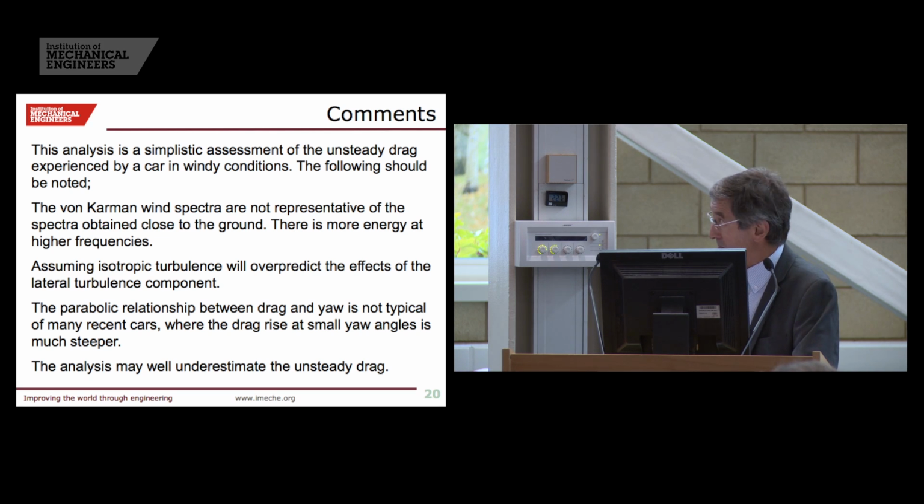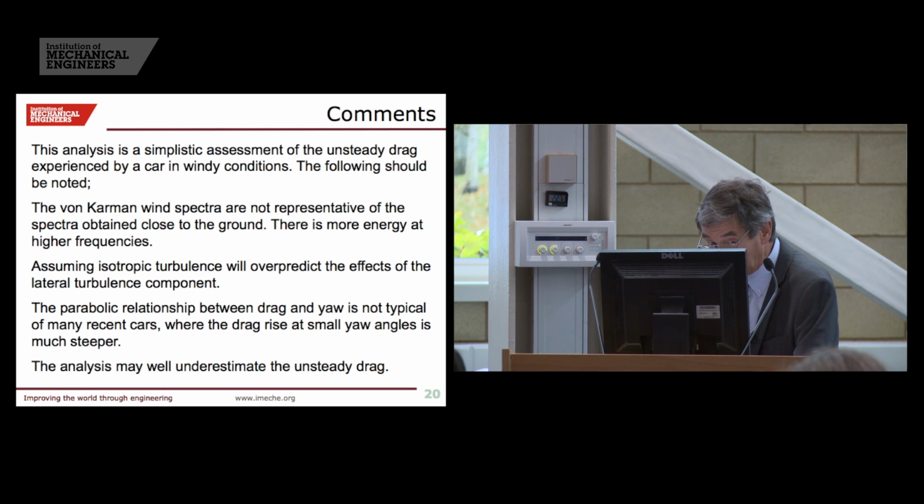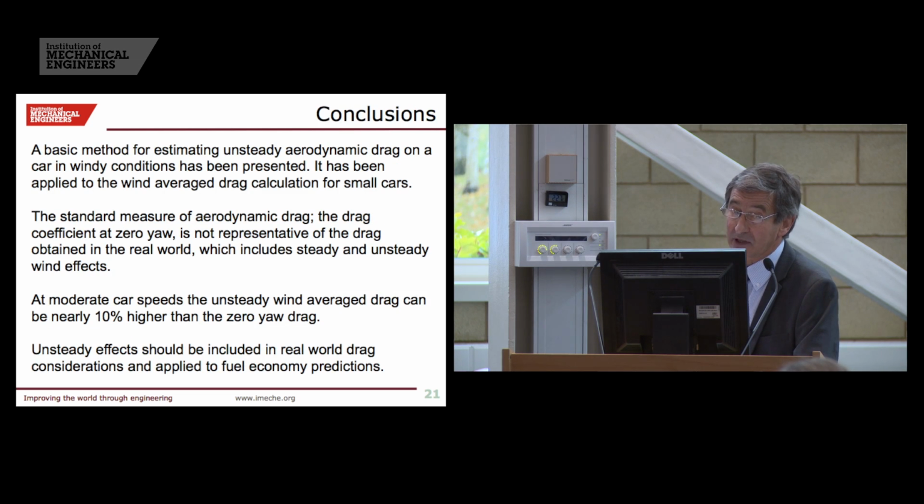And increasingly, this parabolic relationship between drag and yaw isn't typical of many recent cars, where the drag rise with yaw can be very much steeper. And I conclude from that that the analysis may well underestimate the unsteady drag component.